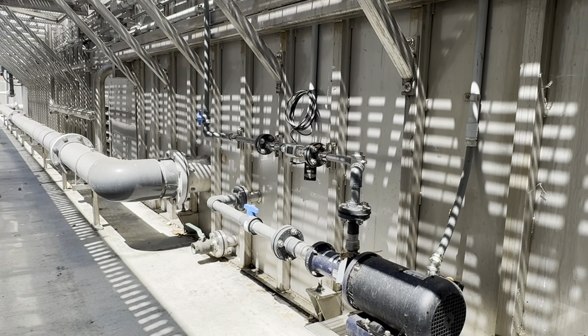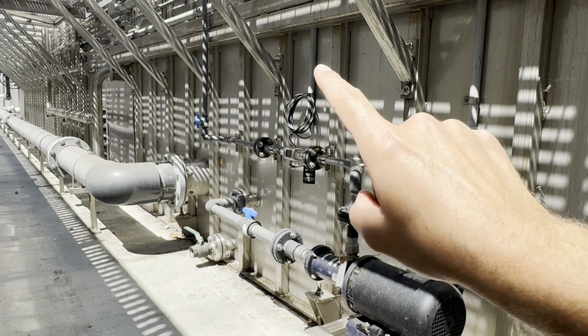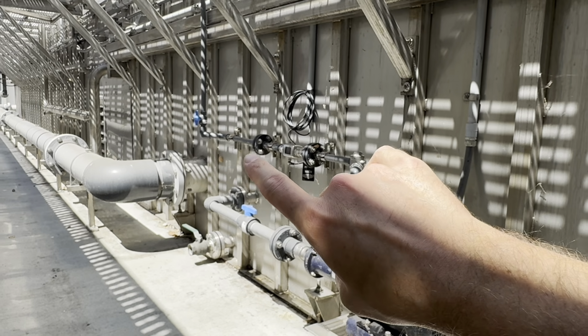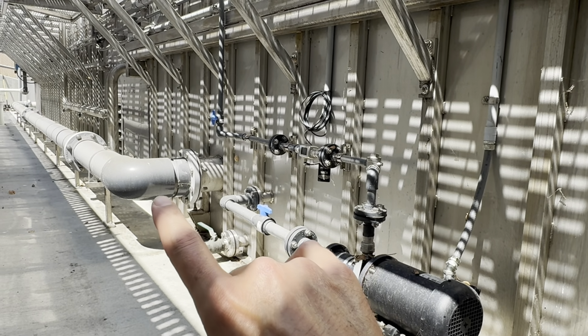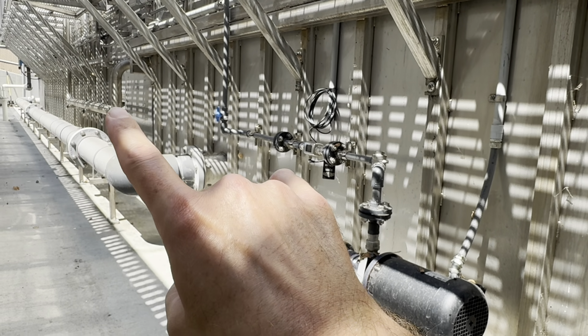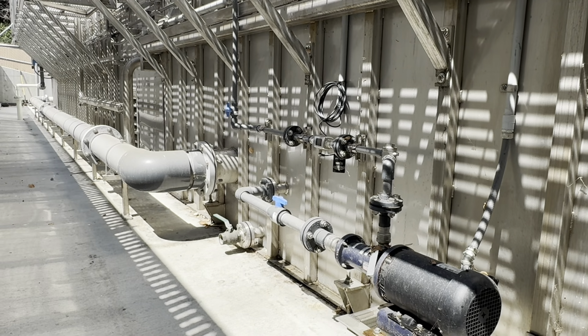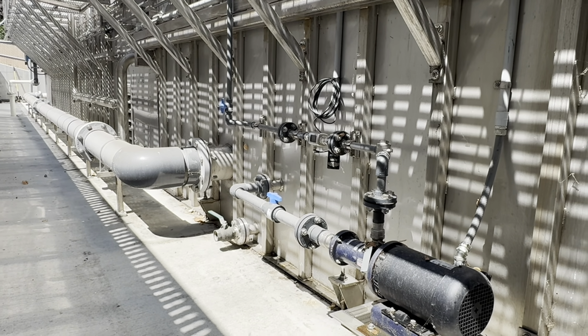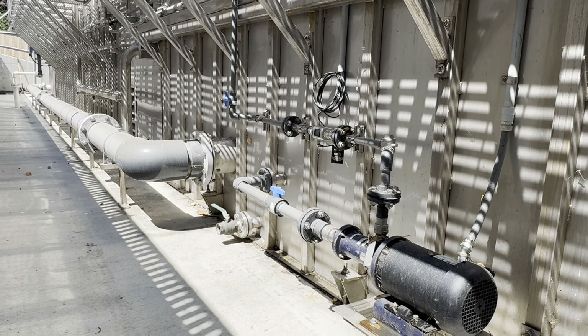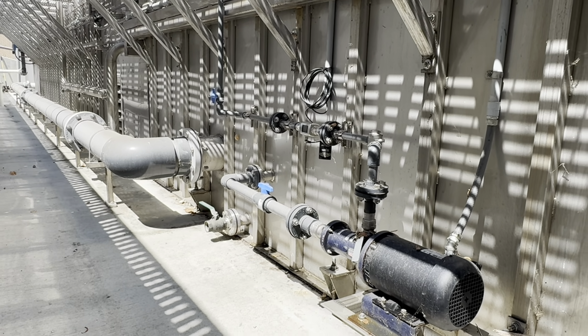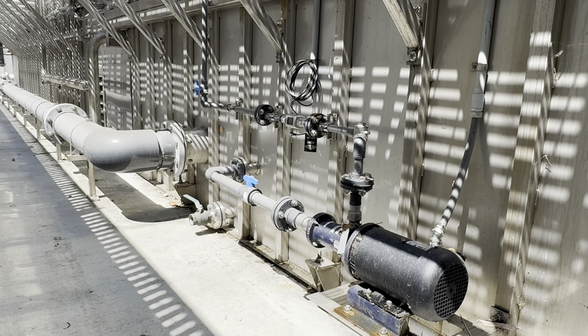Okay, so now we're underneath the catwalk where I was just standing, and that little flow over, what I was calling the RAS, is the return activated sludge. It takes that 8-inch pipe and it heads back to the front of the plant. Now we send it to an anoxic zone. You're going to see on the whiteboard in a minute. In a conventional plant, you would send it to the beginning of aeration. We are a different style. I will cover that in a different whiteboard segment at a later time.